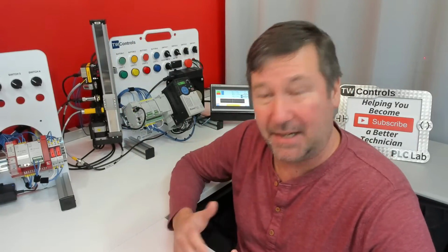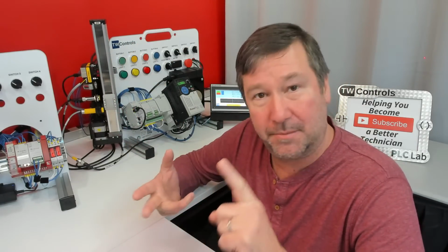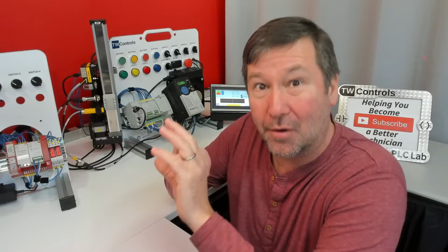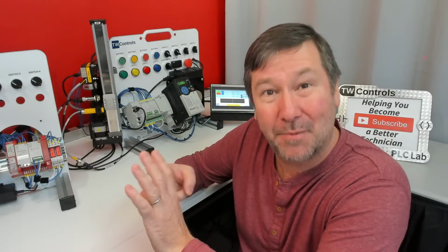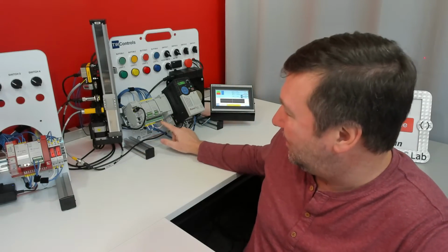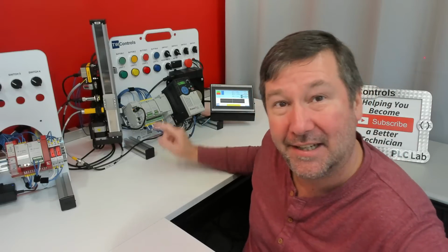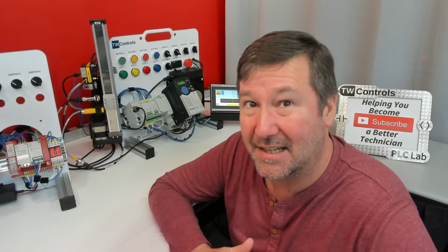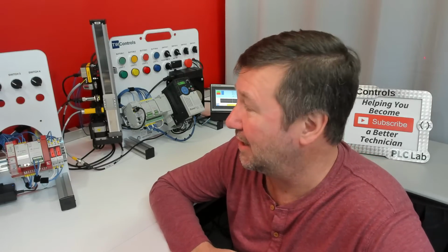It's going to run some type of program, whether it be ladder logic, function block diagram, structured text, or a combination of all three, which is probably what you're seeing more of in modern PLCs. And then it's going to update its outputs accordingly. And then it's going to go around and do it again. It's going to do that incredibly fast. On most PLCs now we're talking about the millisecond range, maybe sub-millisecond.